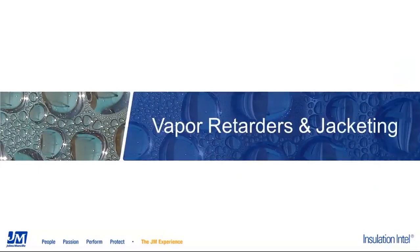Similar to the way that PIR may sometimes be incorrectly referred to as urethane, we often hear the phrase vapor retarder jacketing used. While there are certain vapor retarder products that can also act as a protective jacketing, this is often not the case in an area of mechanical abuse, such as sometimes where a chilled water system exists. Jacketing is usually intended to serve the purpose to protect the insulation system against mechanical abuse. So let's talk first about vapor retarders.